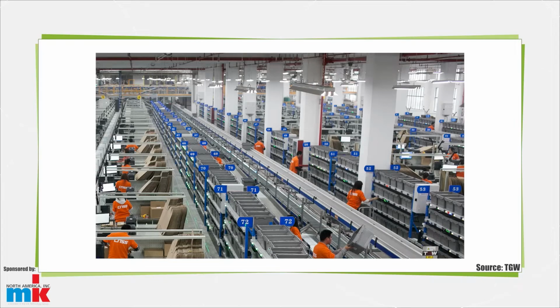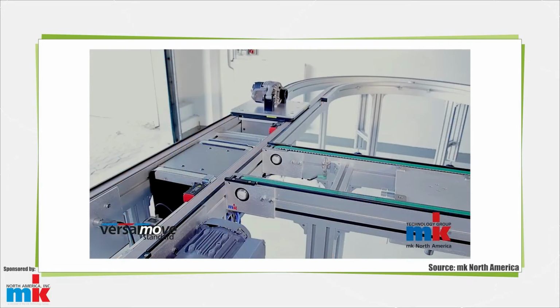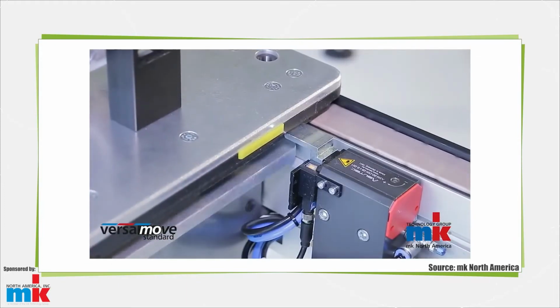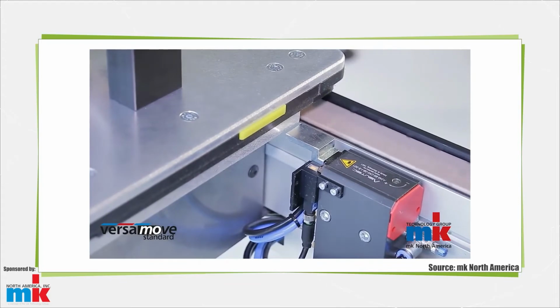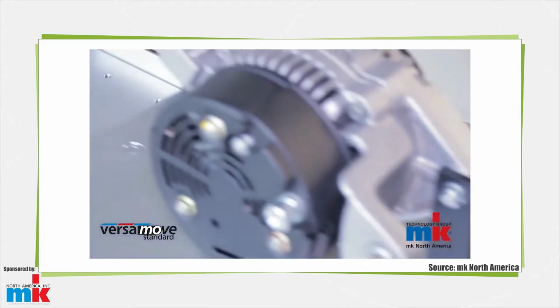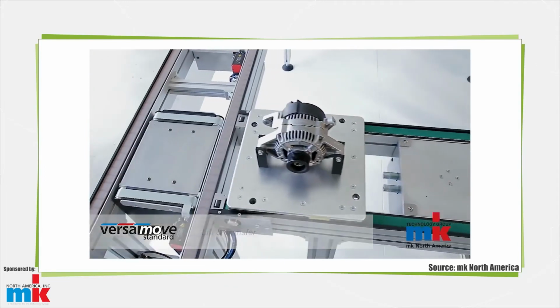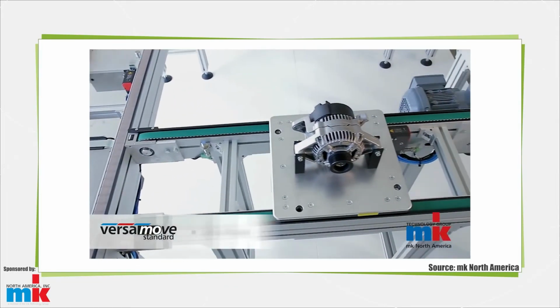Timing belt conveyors use tooth belts that engage synchronous drive pulleys while serving as the conveyor surface as well. These provide excellent belt movement control for accurate part or fixture positioning. Magnetic conveyors are built with ceramic magnets for applications needing parts to adhere to the belt during processing or for jobs that require elevation changes. Higher magnet strength serves inverted applications.